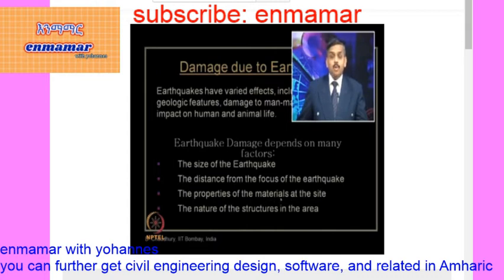Suppose, as I have already given the example of Mexico City, it was located on a soft soil deposit. All the ground structures in Mexico City are located mostly on the soft soil deposit, and the bedrock acceleration at large depth from the ground surface was pretty low in magnitude, which was not supposed to cause major earthquake damage, because the size of the earthquake was pretty small.